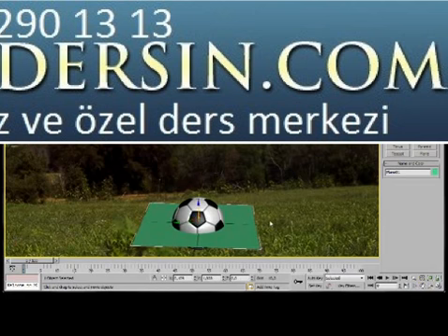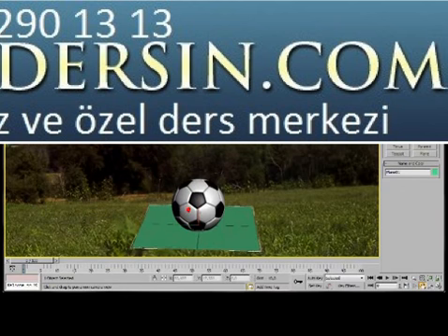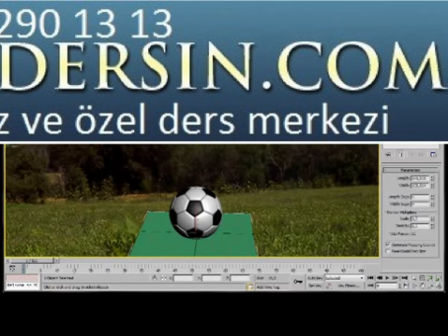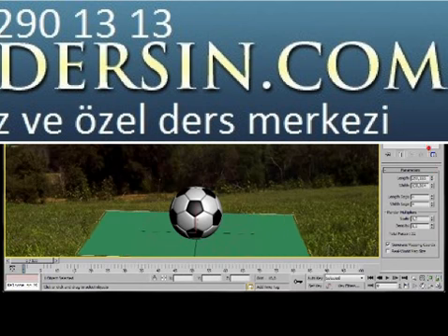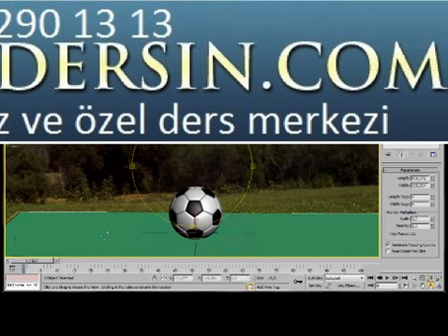Let's adjust the position of the ball. Use the Select and Move tool. We're going to move the ball up, so it's just positioned on top of the plane like that. Use the Pan tool. We'll bring it down. Now we want to select just the plane. Go over to the Modify list, and now we're going to adjust the length. Just by dragging the roller up, we can spread the length right across the image like this. Here we are. I think it's ready now.